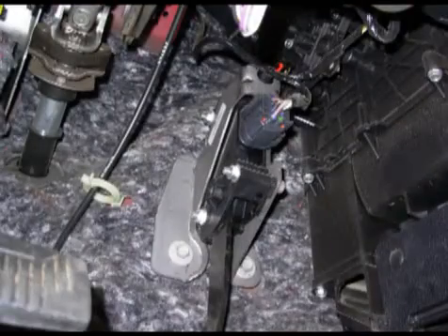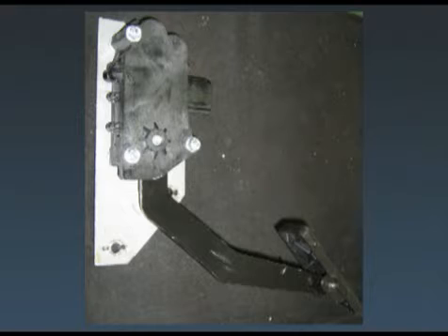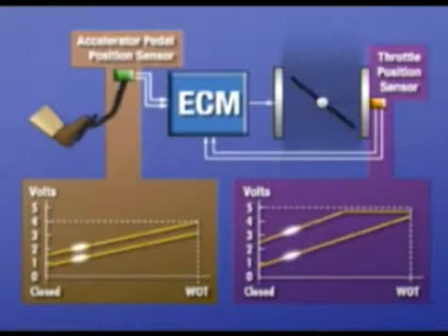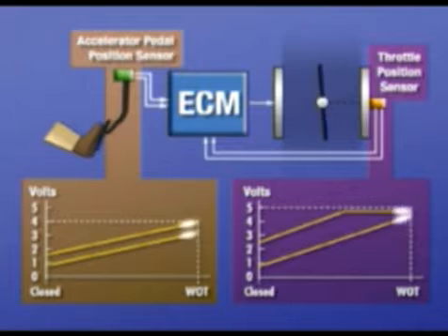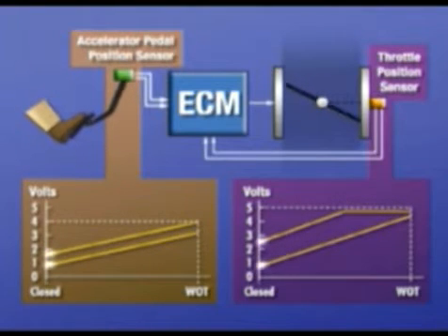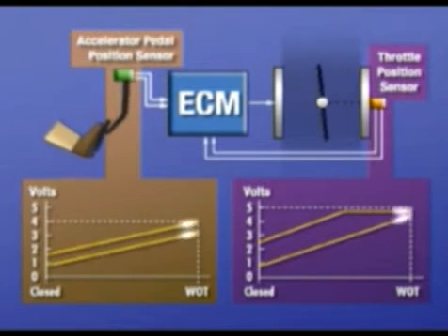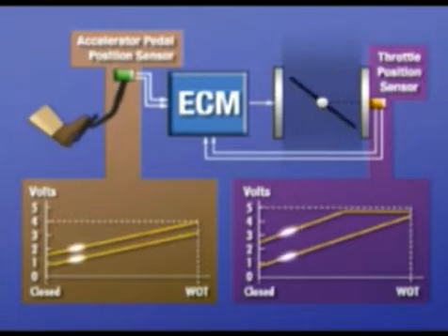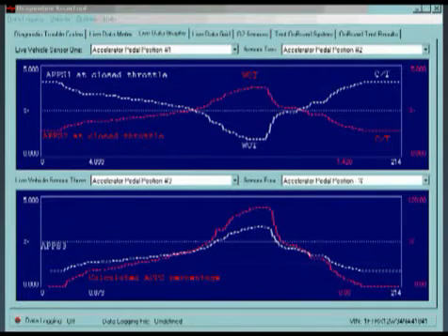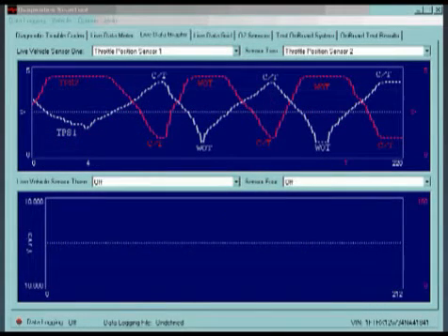In these new systems, the accelerator pedal sensor is an input not only to the engine control system, but to the software system as a whole. The pedal angle or driver input is used to control engine output and by other electronic control systems. The software controlling the anti-lock brakes, vehicle stability, cruise control, HVAC, and other system functions all use pedal angle data in a decision-making process. The throttle angle that results is not only what the driver wants, but what the system needs for correct and safe operation.